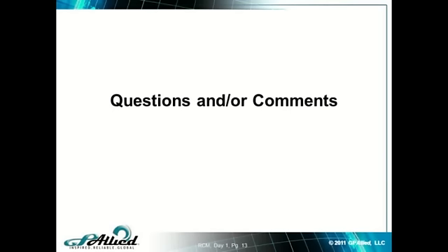If we hadn't improved the installation, that probably had the largest impact on the mean time between failure, but it also gave them a point in time where they could now start using some of the predictive tools that actually work. It also was a point where they could use some of the proactive tools like precision alignment. This particular company had tried precision alignment on many, many occasions, to the point where the maintenance guys said, well, we can precision align the pump that's there, but two weeks later it'll be out of alignment. The precision alignment stuff doesn't work. It helps initially, but it's not going to hold, right?